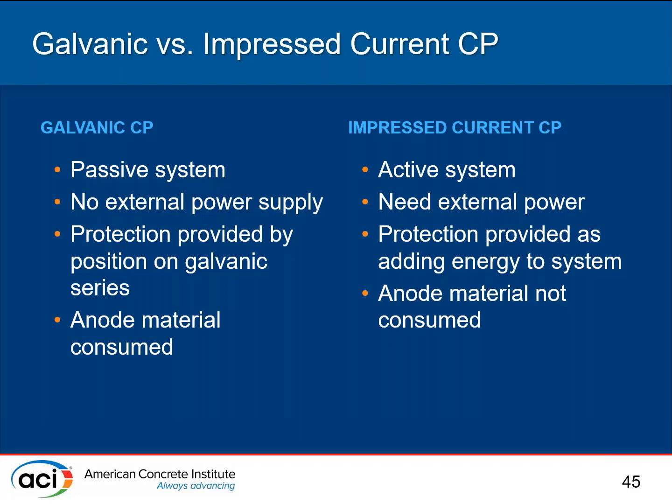Someone bumps your wires. But theoretically, you design your galvanic system for a certain lifetime, whereas your impressed current cathodic protection system can go for a lot longer if everything behaves the way it should. Simplistic, there's a lot more details that go into CP, but that's the 2-cent version of it.